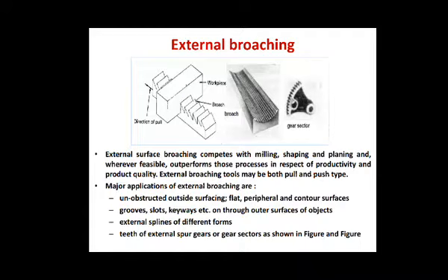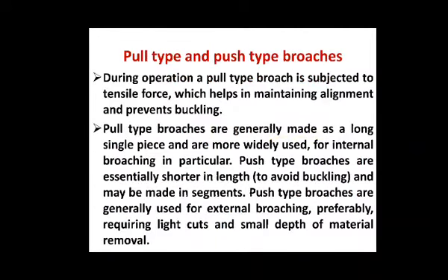Okay, so let us see next the pull type and push type broaches. Pull type broach is subject to tensile force which maintains alignment and prevents buckling. Pull type broaches are made as a single long piece, and these are widely used for internal broaching, and push type broaches are shorter in length to avoid buckling and made in segments. Push broaches are used for external broaching, preferably requiring light cuts and small depth of material removal.